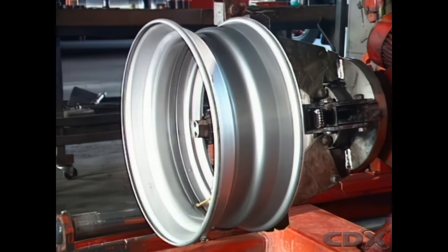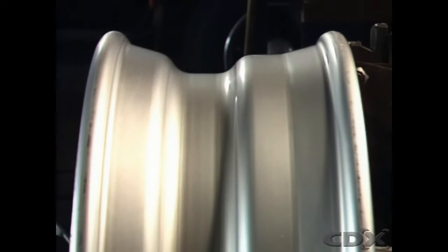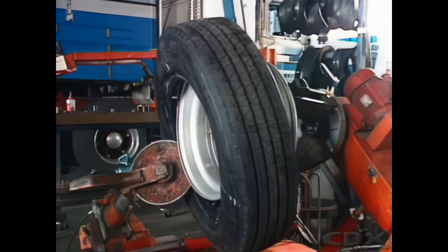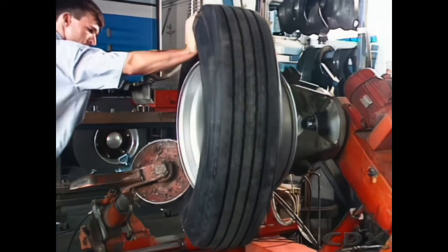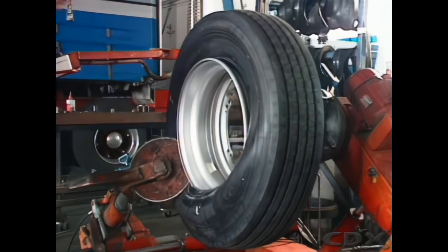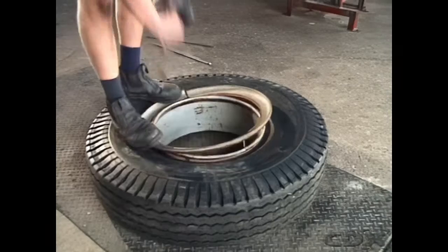Well-based rims can also be used on heavy commercial vehicles for tubeless tyres. The rims are referred to as 15-degree drop-centre rims because the bead seats are inclined at 15 degrees towards the flange. The taper gives a good grip and an airtight seal between the tyre beads and the rim. The low flanges and drop centre allow the special size, flexible tubeless truck tyres to be mounted and demounted in a similar manner to that used on smaller passenger car tyres.